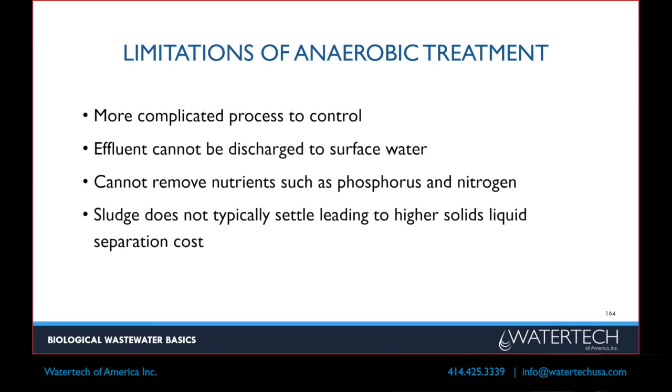Again, for me, it's a little bit more complicated process to control. People that know it and do it are pretty comfortable with it. I don't know that you can't, but it doesn't remove as much organic matter. It doesn't treat down to the levels of COD or BOD that an activated sludge system will. So it's in that more complicated system that I showed you where they have both aerobic and anaerobic. The clean water that comes out of the anaerobic treatment then gets fed into the aerobic to be treated to a level where it can be discharged to the surface water.